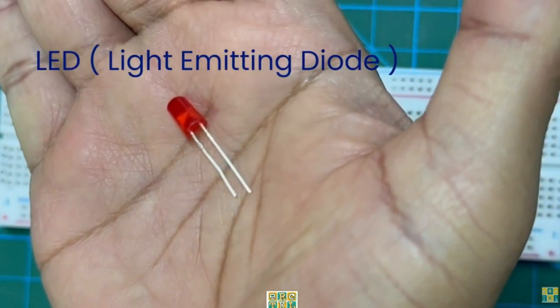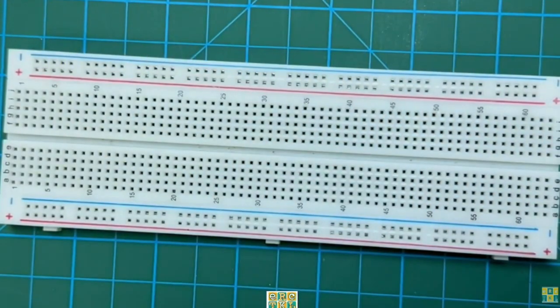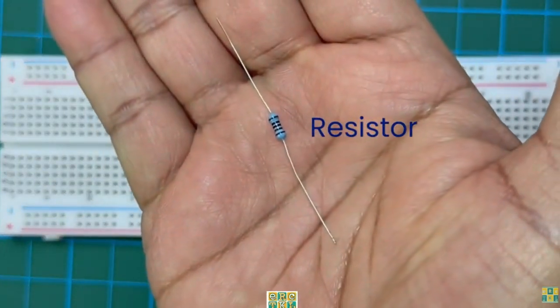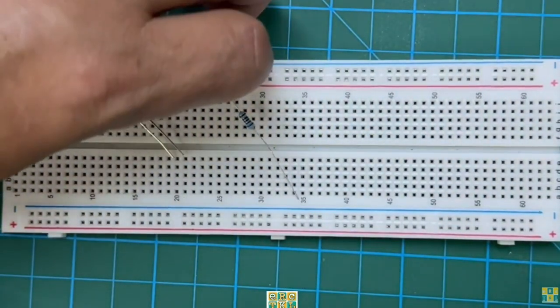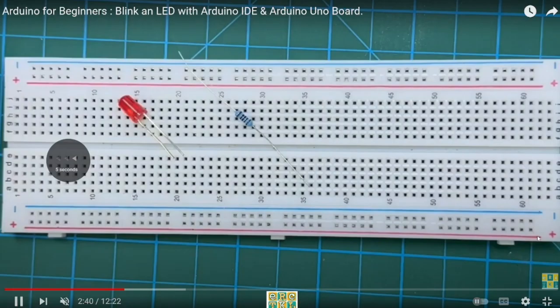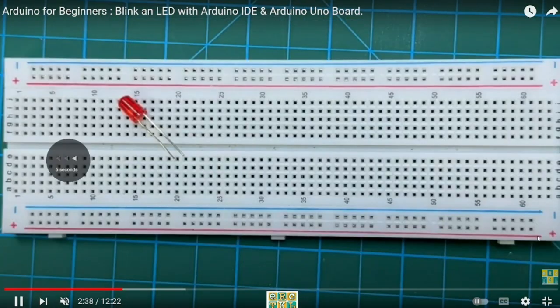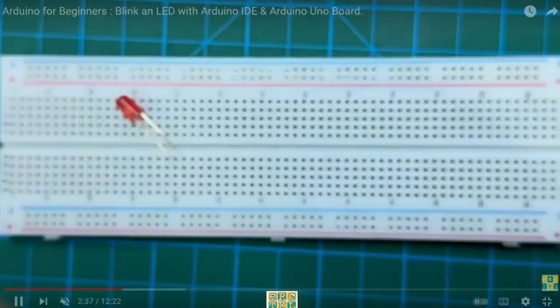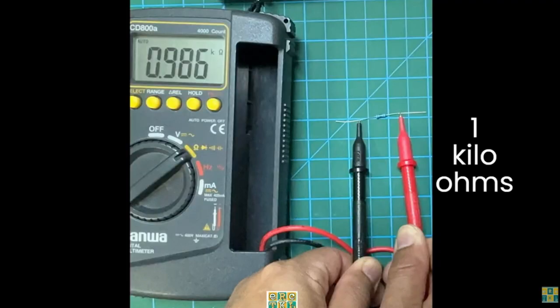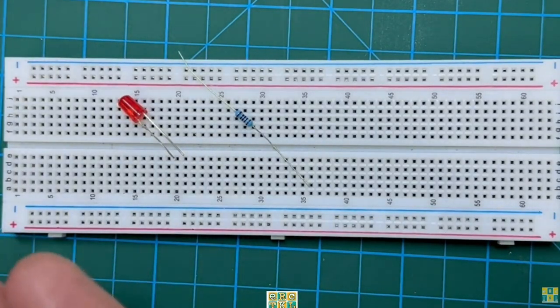Now, this is the LED or the light emitting diode. And in the LED, as you can see here, we have the anode and the cathode of the LED. The shorter one is the cathode. Now, if we go back a little, we have the resistor, and the resistor that I used here in this example is actually 1 kilo ohm. Okay, we need also to measure it. So this is a 0.986 kilo ohm. Actually, it's approximately 1 kilo ohm.